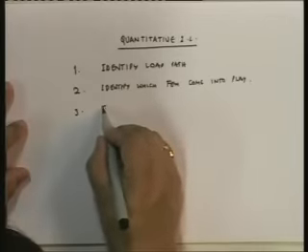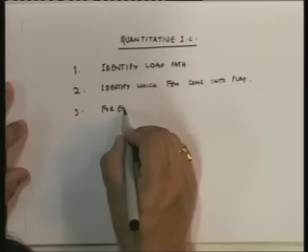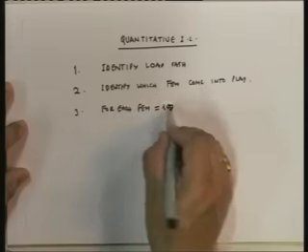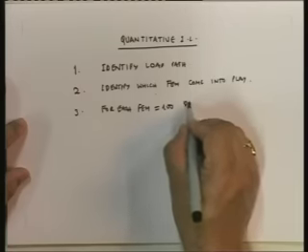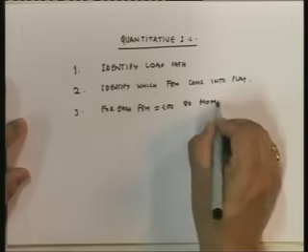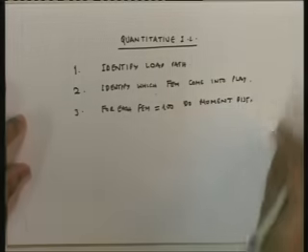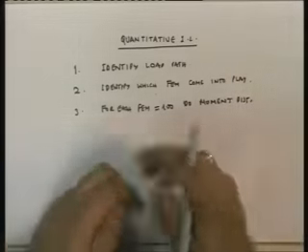Then for each FEM equal to 100, do moment distribution. As many points as you develop fixed end moments at, you are going to get that many moment distributions.